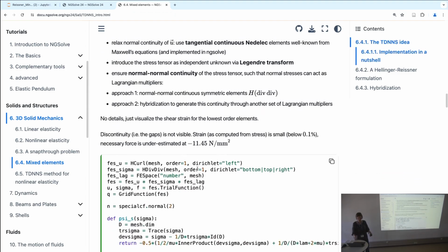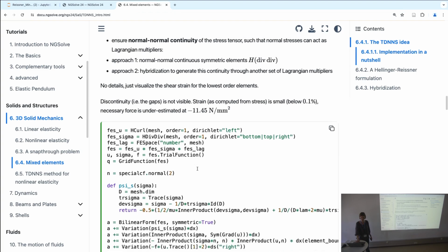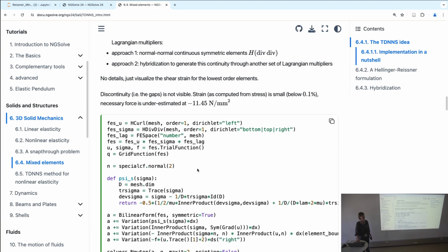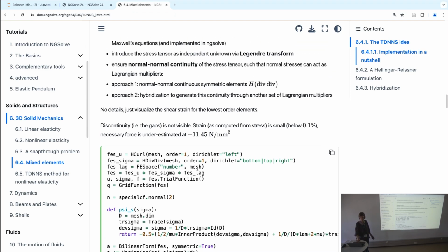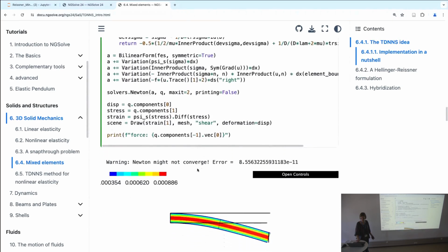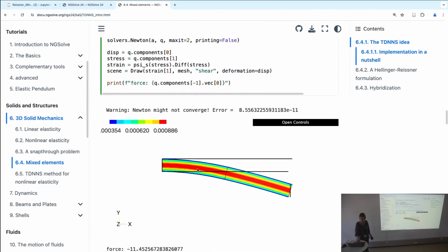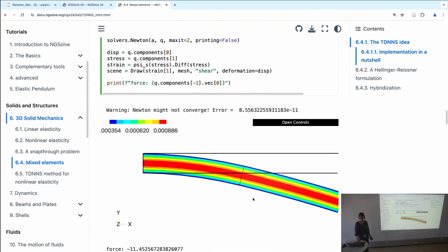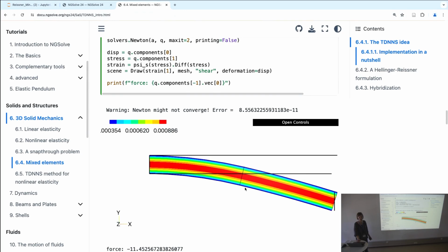And then we transform the system, the principle of virtual work, to a Reissner type formulation where we have stresses and displacements as unknowns. We do a Legendre transform, and then we do the computation. And then when we do, again, for linear, so for lowest order elements, the degrees of freedom are linear, the shape functions are not.